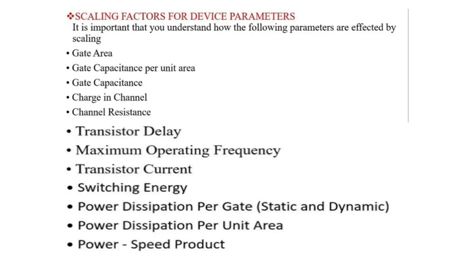Smaller devices generally operate at faster speeds and consume less power. Power consumption: when we go for supply voltage scaling and dimension scaling, power dissipation can be reduced significantly. And finally, lower manufacturing cost. Transistor scale down can lead to more efficient chip manufacturing and lower cost per chip.